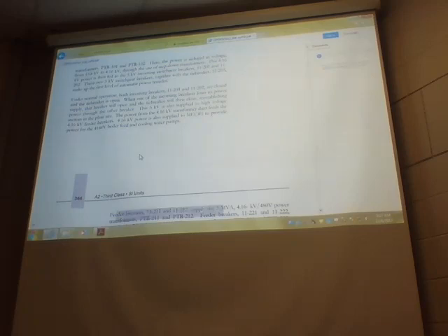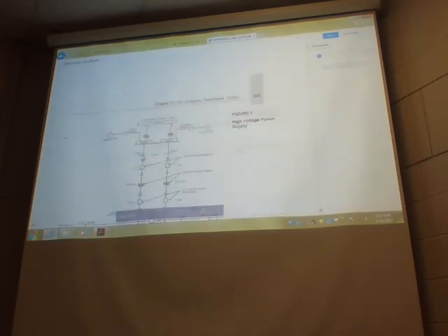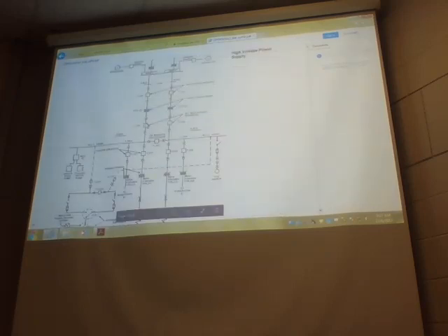So if we're looking here now, if one of these breakers fails or is open for some reason, so you don't have both A bus and B bus feeding, normally these are closed, so there is power feeding through both of them, and this is the tiebreaker that is open, separating the two.